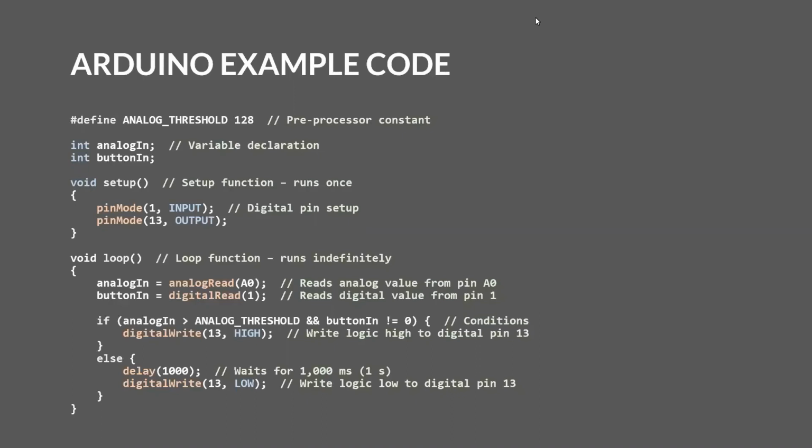In general, you should try and avoid delays in microcontrollers, especially using this form of delay, because this delay is essentially implemented as sending a bunch of what are called no-ops or no-operation instructions to the CPU. And so the CPU is continuously doing stuff throughout that delay, and it's using power, but you're not actually doing anything useful. But in some cases, it's useful to have a short delay.